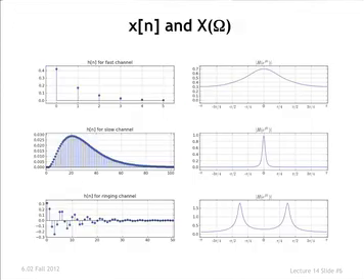If you look at the top plot in this set, it is exactly a signal of that type, except I've chosen a different number. Instead of 0.5 to the n times u of n, it's something else. But here's a discrete time exponential or a geometric series. Now I've just plotted the DTFT from minus pi to pi to show you what the spectral content of the signal is.